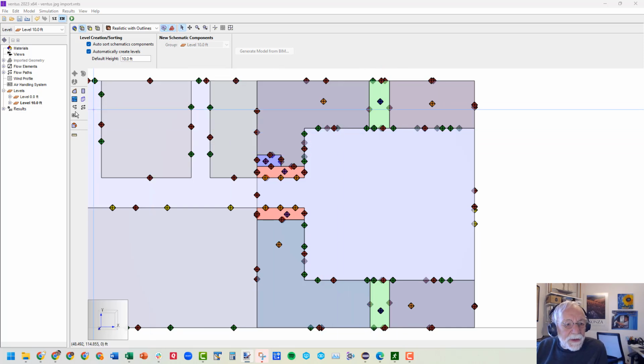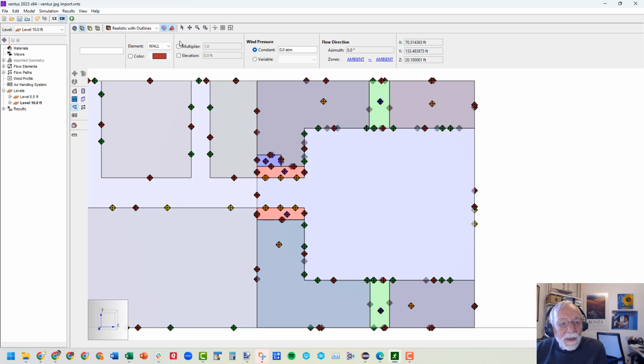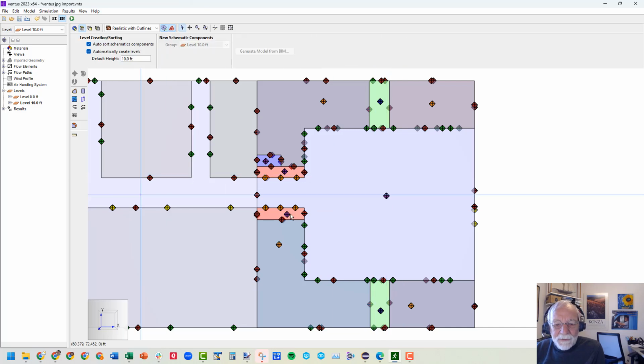Okay, so what I'm going to do is select the single flow path here, and select the existing elevator, but then change the multiplier to 10. So this flow path through the atrium to below is going to be 10 times the flow path for the elevator shaft. That seems like a reasonable approximation. It doesn't seem like too large a number, and yet it should give the kind of desired easy flow through the flow path.